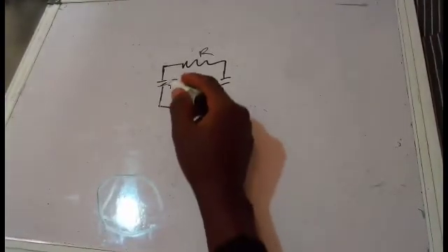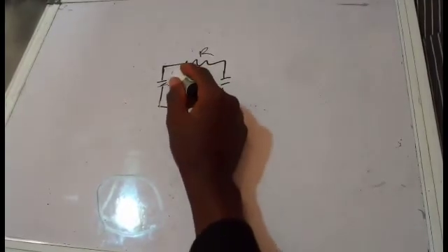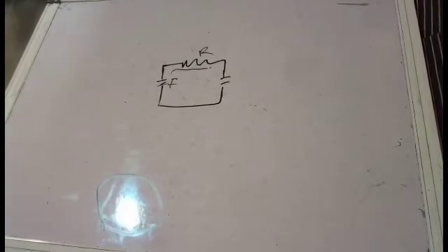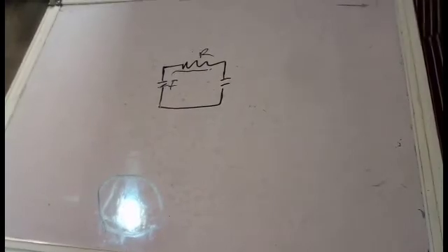Now, that same charge will flow across the resistor. At the point where there's a sudden stop to the flow of current, we call that a transient circuit. Now, a source-free circuit occurs when a DC source is suddenly disconnected. The energy already stored in the capacitor is released to the resistor.